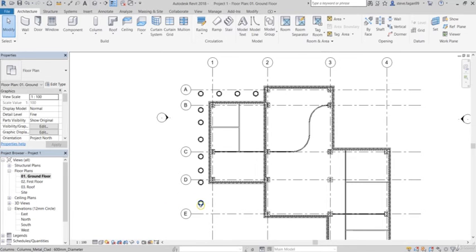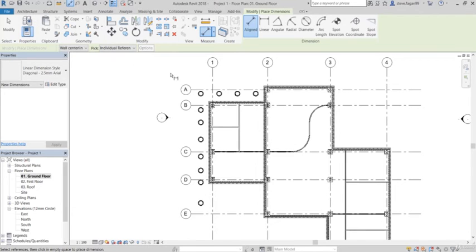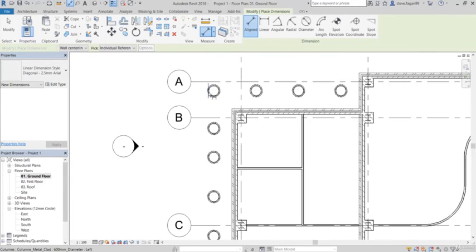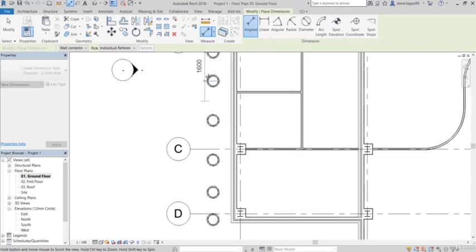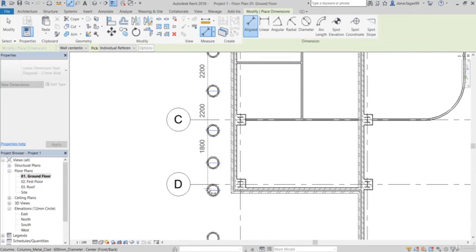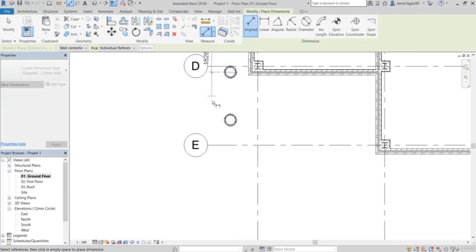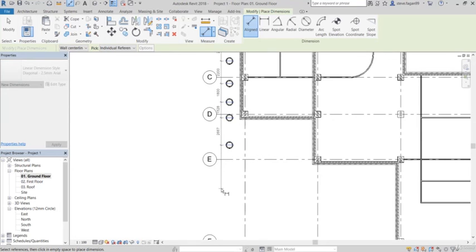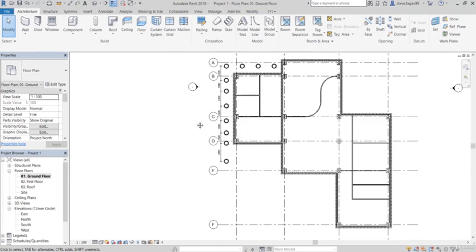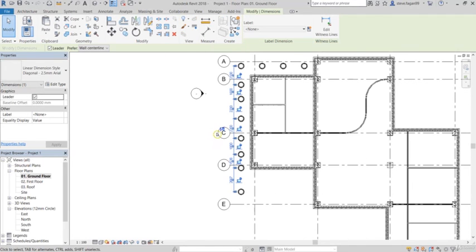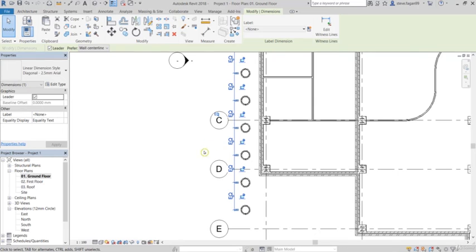And now that I have the position of the last one, I can use the same aligned dimension tool. Because I'm doing a vertical distance, I now have to get a horizontal blue line. So there's my vertical, there's my horizontal. Again, just clicking once to place, using my wheel on the mouse to pan. And once I've got the last one, just moving the dimensions in the correct position, moving the cursor away from any other object so it won't select, and left click with the mouse. So now when I select the dimension run, there's that EQ, click to place, and it will equally space the columns.